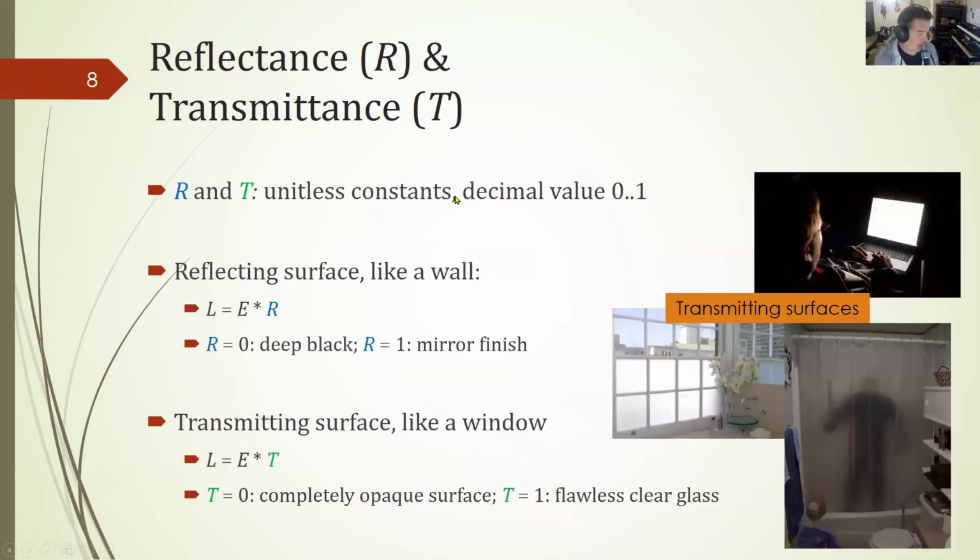All right, here we go. So here's our math. We have these constants, and these are values between 0 and 1. They have no units, which works out pretty nicely mathematically when you're comparing things like foot candles and foot Lamberts, and you're thinking, how do I get from one to the other? Well, if you've got a nice unitless multiplier, and you recognize that mathematically we're talking about lumens per foot squared in each case, that's how it works out.